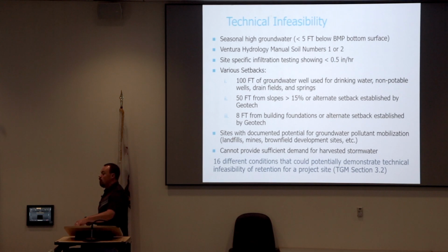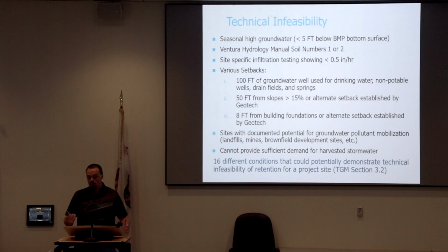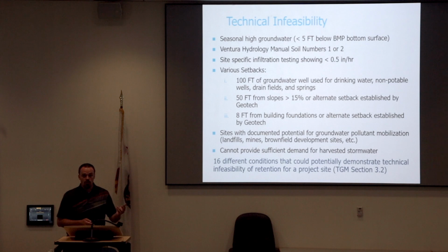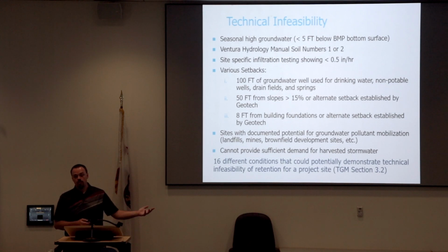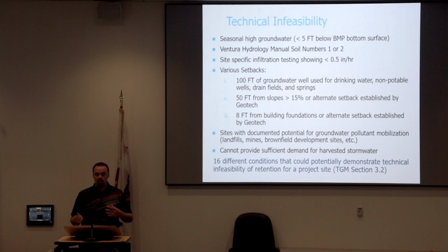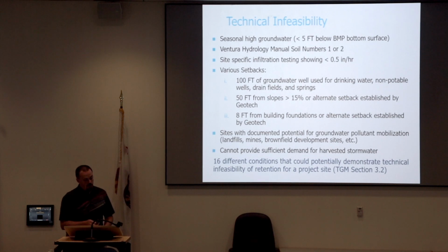testing. I always recommend infiltration testing. The TGM doesn't require it, but it does make a lot of sense, because not knowing how quickly water is infiltrating can make a huge impact on your project. I'll show you a couple of examples later on of where I thought I'd have good infiltration for one of the projects I was managing. I did a minor conceptual design, went for grant applications, and had to change the whole thing after we did infiltration testing. So we'll go through that.